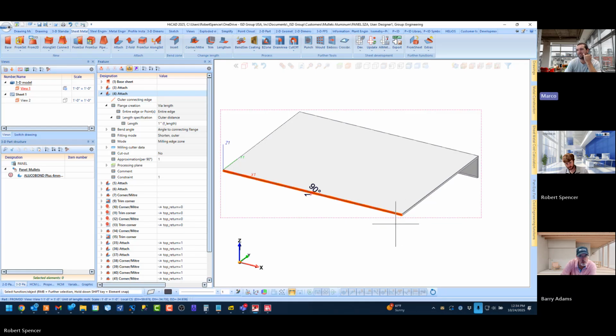I usually miter the first inch of it, if it's a longer flat, so when it gets into that corner, it sits okay. Just for a little more freedom. Yeah, that, or just back off the flange an 1/8 inch, 3/16, whatever, and it clears too. Okay. Depends on the scenario.